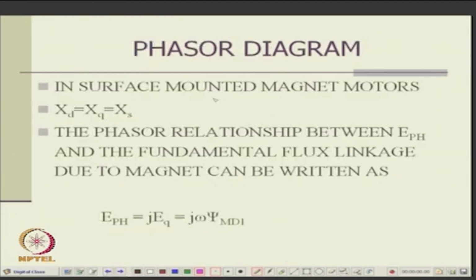In surface mounted magnets, there is no saliency, the magnets are just mounted on the surface, but sometimes if you make cuts, then it will create some saliency. There you assume that whatever may be the position of the rotor, the synchronous reactance of the stator will remain the same, because the flux pattern will not change, isn't it? But if it is purely salient, then it will change, because whether the D axis is aligned or the Q axis is aligned matters to that winding.